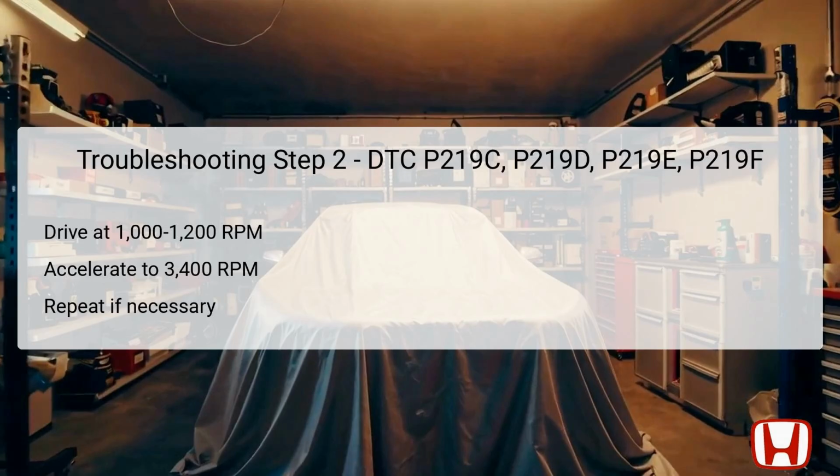Repeating this acceleration process multiple times ensures that consistent data is gathered, allowing for better diagnostic accuracy. Ideally, observing how the PCM adapts to changes during this acceleration can provide insight into potential air-fuel ratio deviations in any of the cylinders. If any variations are recognized during this process, it may bring to light the cylinders with abnormal ratios, guiding further inspection and repairs.